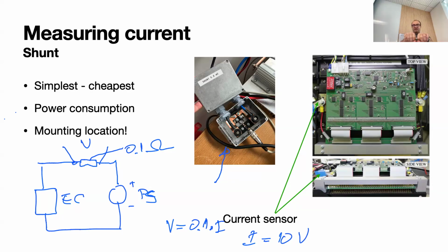It's not a resistor like you're used to seeing, a tubular cylindrical thing, because those resistors have some inductivity in them. It is a PCB-like, chip-like unit that has practically no inductivity and no capacitance. It has some, but it's really low, and you can neglect this capacitance and inductivity up to very high frequencies, I think towards megahertz level, which means it will not affect the measurement of our impedance.